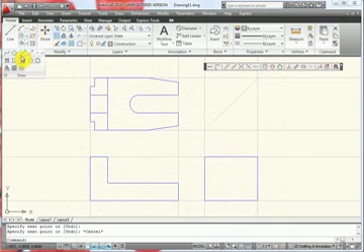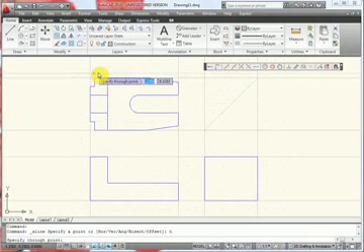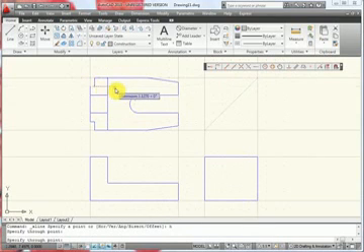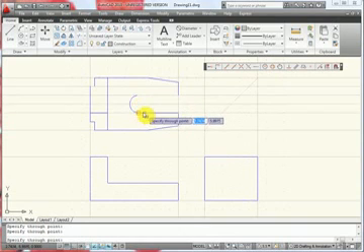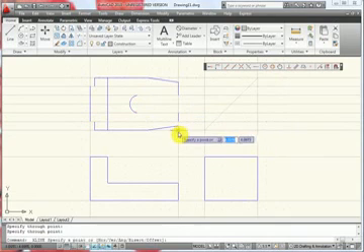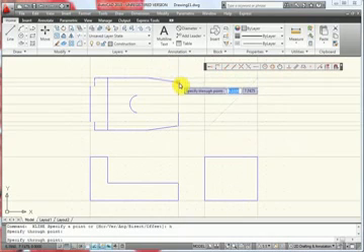So I'm going to get out my construction line tool. I'm going to make horizontal lines. I'm going to put an H for horizontal, and then with this top view, anytime I run across any type of horizontal geometry like this back line, I'm going to make a construction line for it, as well as any type of center line like the center of the circle. One more line I have to make for this point down here, and I forgot to point it up here.